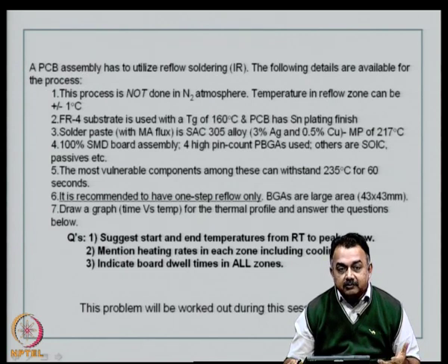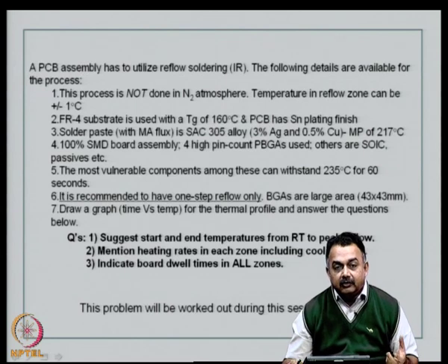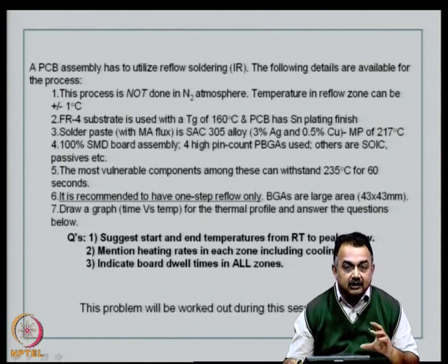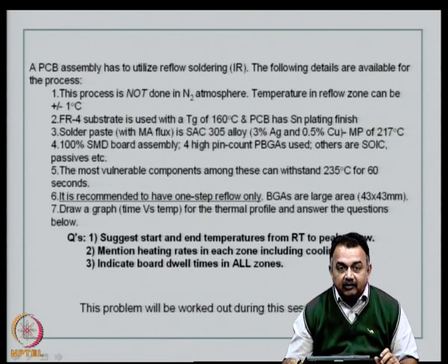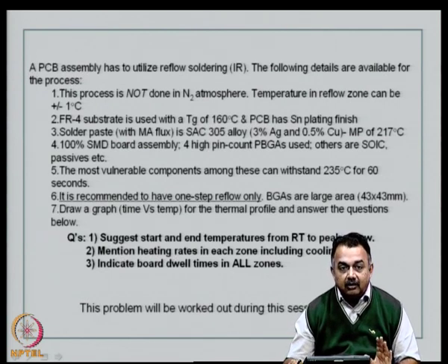Very often the board is manufactured and then you give your components to an assembly personnel in a EMS, and then if you do not interact with them on the subtleties involved, which will make a large count for reliability, then you have problem. Therefore, I like to spend a few more minutes on understanding thermal profile, because as a designer, if you can give this information to the EMS, then your board comes out well assembled.